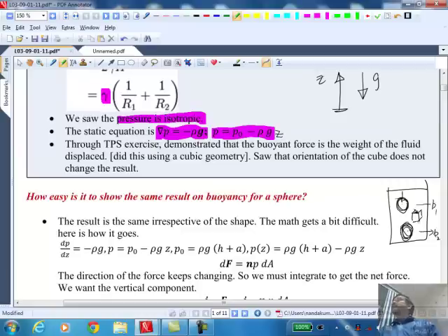So we pick the surfaces in such a way that you have a flat, uniform surface. All the forces are pointing in the same direction. So all you have to do is take the force at the top surface, which is a constant pressure, multiplied by the area, which gives you the force. So you can do it algebraically. This is what one would do at the undergraduate level. Everything is simplified to algebraic equations because you don't want to deal with differential equations. Here you have to deal with differential equations. So I'm going to ask you to calculate the same buoyancy force on a spherical particle.